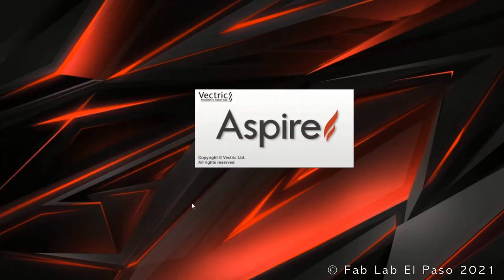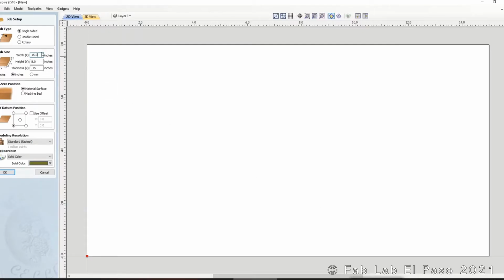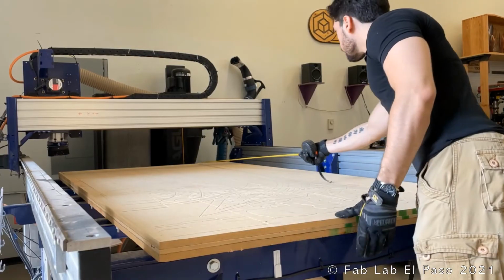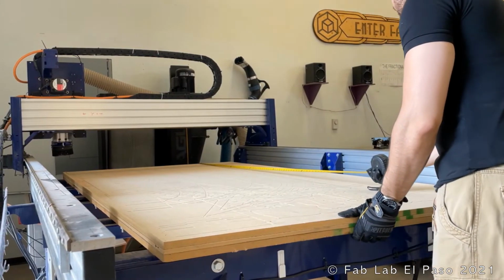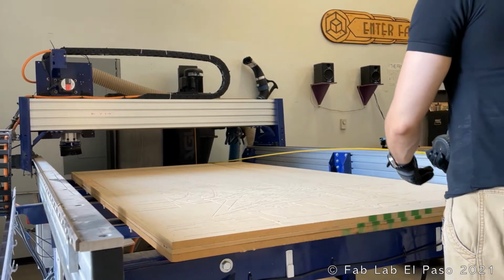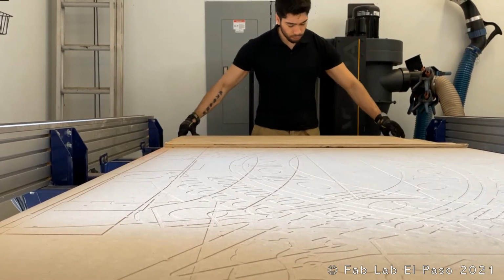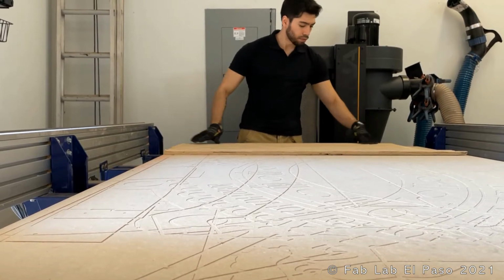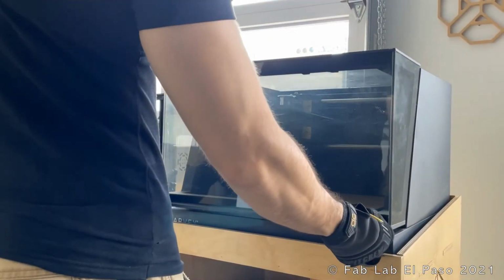So let's open Aspire and create a new file. Depending on the part that you'd like to do, the size of the canvas differs, but you must know your machine. At FabLab, we have two CNC routers. Here at the workshop, we have our CNC machine with a workspace of 8 feet by 4 feet and 6 inches tall. It is important to know this because if you have a machine that is capable of only smaller areas, then you need to reconsider the strategy of manufacturing your job, like this small CNC.